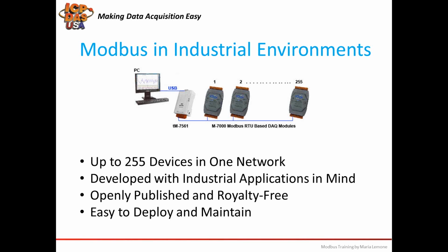So if you already have a big network of Modbus RTU devices, then you can just add more Modbus RTU. Or if you already have Modbus TCP, you can add more Modbus TCP. Or like Khan mentioned, if you want to add TCP to the RTU networks, you can use a TGW715, which is a Modbus TCP to RTU gateway. And also for the TCP networks, if you want to add RTU devices, you can do the same.